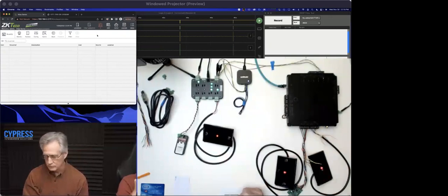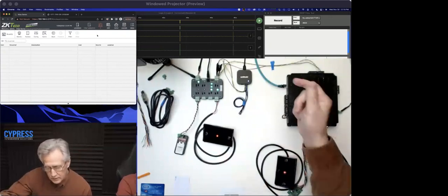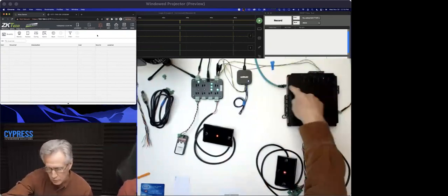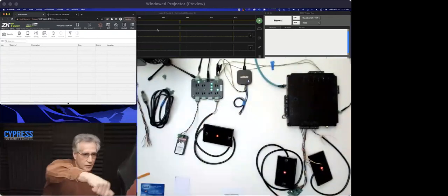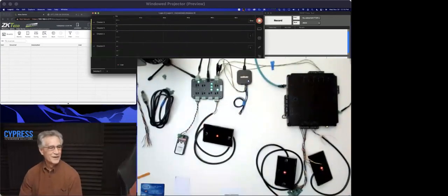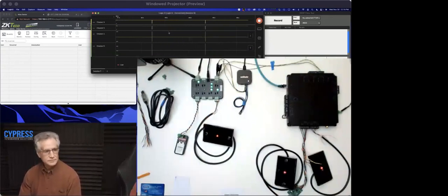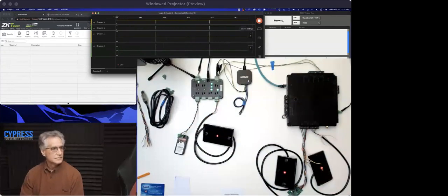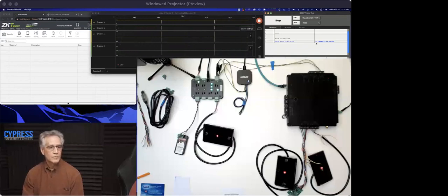So we're going to go ahead and, you just hit the green button there. That's right. Okay. So we can see something's happening on the line, which we would assume is the panel trying to poll or communicating on the Saleae device. If we actually hit record on the trace tool, we'll actually see a PD capabilities request.